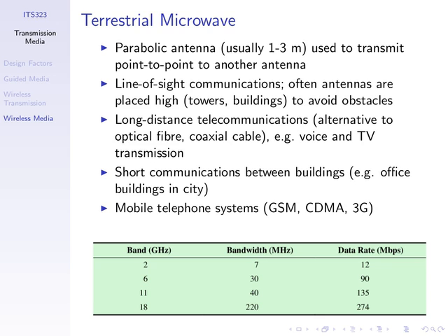And using point-to-point communications, the antennas are highly directional, meaning the signal transmitted by this antenna goes in one direction only. That is, it's strongest in that direction. In other directions, it's very, very weak. So to communicate, both the transmit and receive antenna need to be pointed at each other. Because if we misalign the transmitting antenna, the signal will go in another direction and will not be received by the receive antenna.